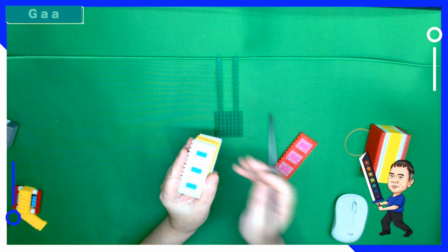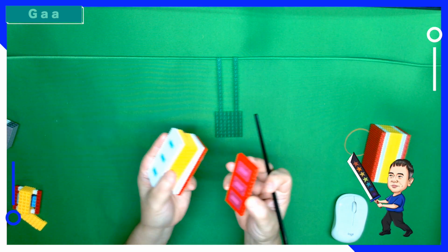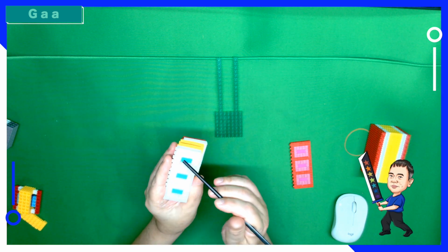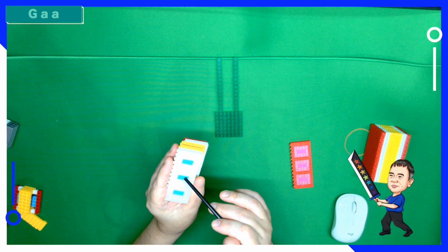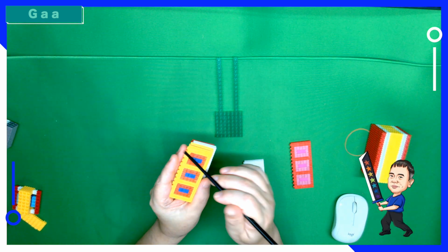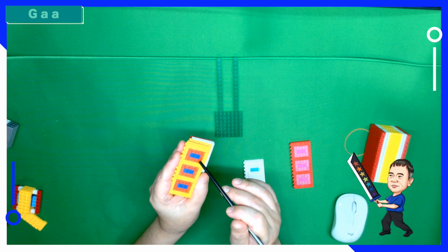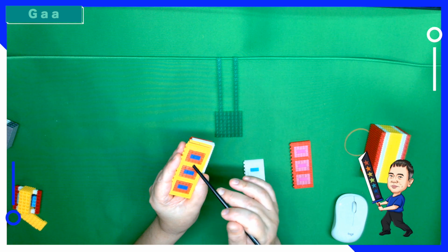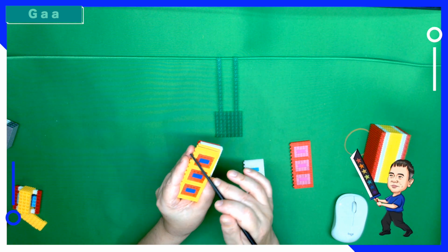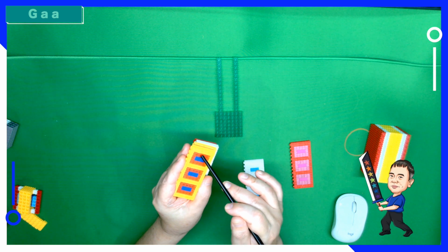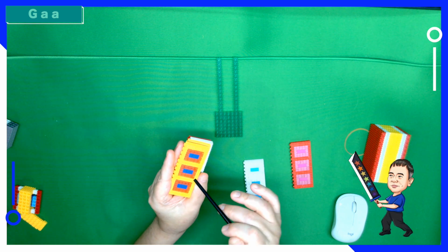So I take it apart, and you can see here's the source and the drain, and here's the bridge. One bridge, two bridges, three bridges. I take a slice down, and here's the gate. If I look around each of the bridges, or each of the channels, the gate totally surrounds the bridge with the oxide layer in between.